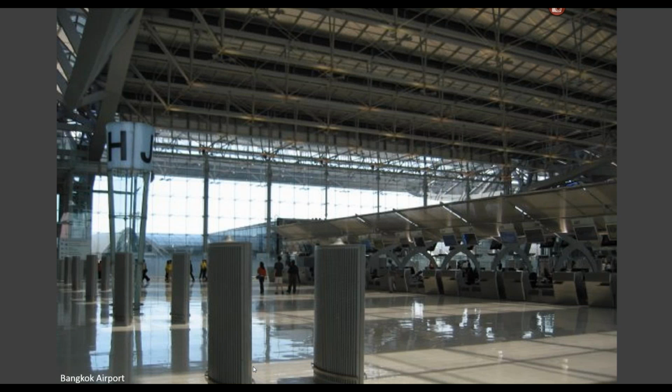the occupied space. And so what that allows us to do is we're only treating the occupied space. We're not going to waste a bunch of energy trying to treat the ceiling space, get the air down to the occupied space, fight all that distance, fight all that delta T. We're just going to introduce our 61 to 70 degree air right at the occupied zone where it's needed. And that's again where some of the energy savings potential of displacement products come into play.